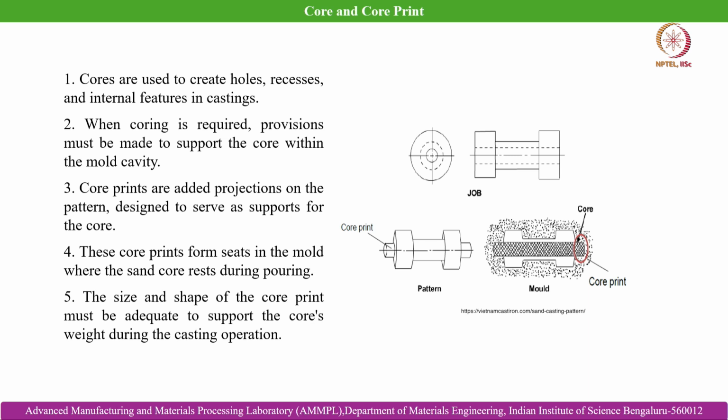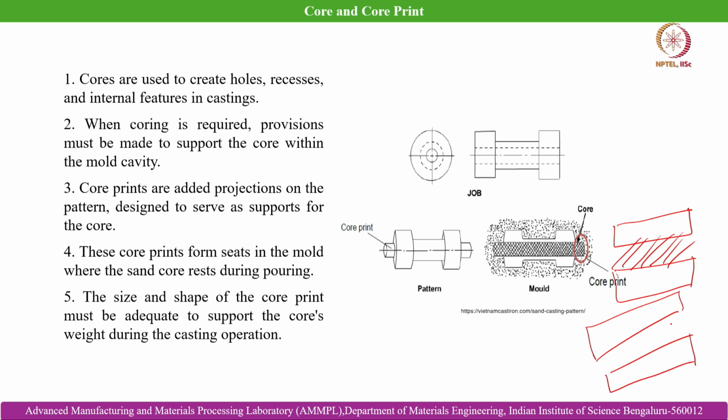For example, this is a straight cylindrical hole that is needed in this case, and this is the core placed inside. If it is not supported by core prints, this can cause an eccentric hole in the component upon solidification, which can cause rejection of the cast part, because there is no means, even by doing significant machining, to achieve the desired dimension.